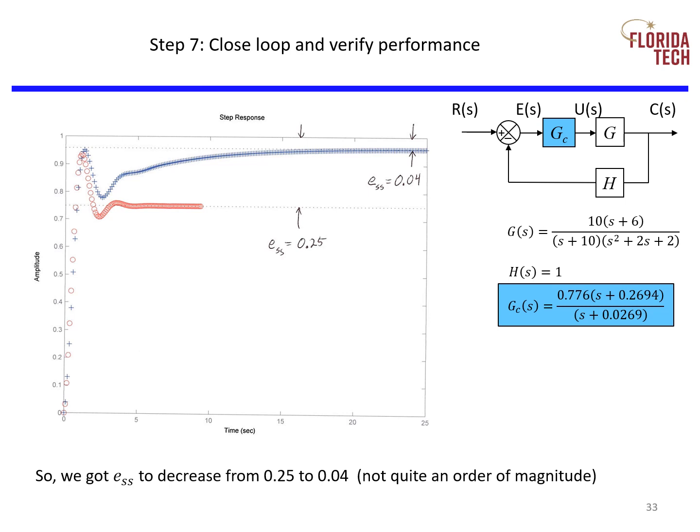This concludes the module for lag controller design. I do want to make one note. MATLAB does not have a built-in command to generate a ramp response. You're going to have to visit my YouTube channel to see how to make MATLAB generate a ramp response by putting an integrator, 1/s, in series with the closed loop transfer function and then using MATLAB's step command.